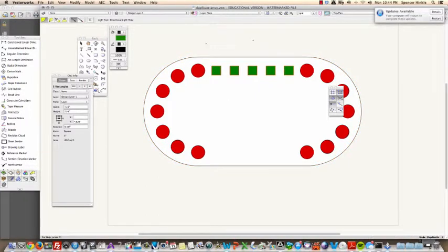So now let's do the rectangular array. Now we're going to do it two ways. The first way, since we have these here, we're going to consider this as one column. And when you do rectangular arrays, you think in terms of rows and columns, just like a spreadsheet. The rows are running horizontally. That would correspond to the x-axis, and the columns are running vertically, corresponding to the y-axis. But we're going to think of this block of 5 here as one column.